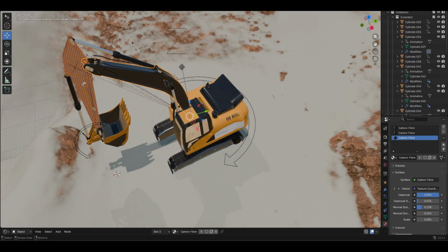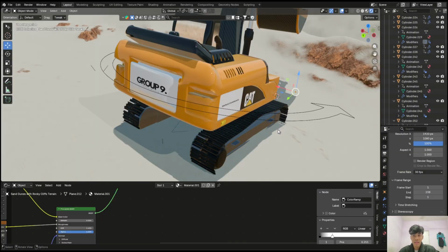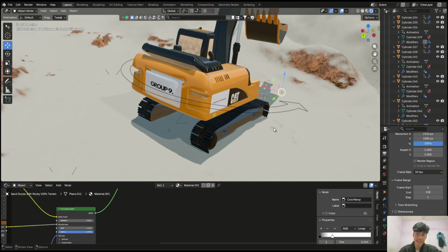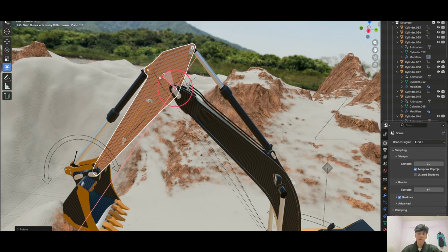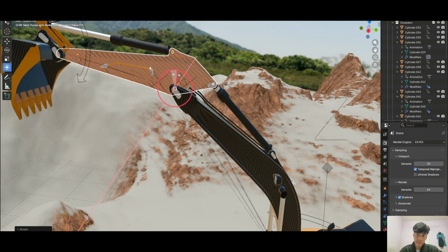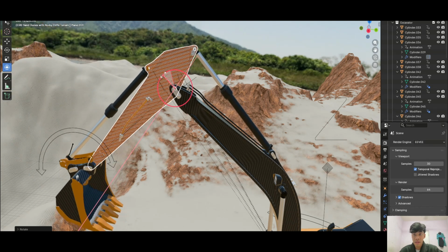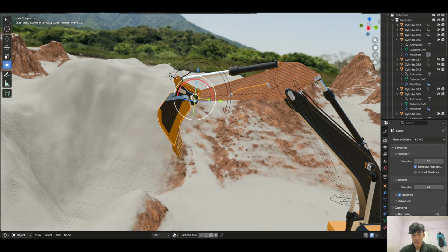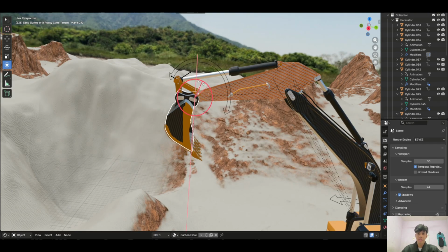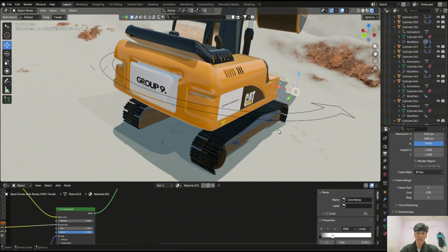The individual metal plates are called shoes or links. They are joined together by pins to create a flexible chain. The smooth wheel at the front doesn't have power, it just guides the track and keeps it tight. The excavator laying its own road is the coolest way to describe it. The track lays flat on the ground and the wheels roll over the track like a temporary road.